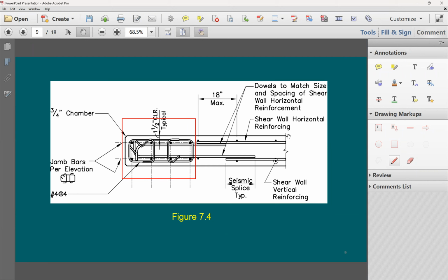So, okay. How about this rho n? What is that? I'm going to say this is to account for the shear strength from the steel. Shear strength is going to be equal to the shear reinforcement ratio times F sub y times ACV. Just to remind you, AS equals what? In this equation, AS is going to be equal to the steel ratio times A sub CV.